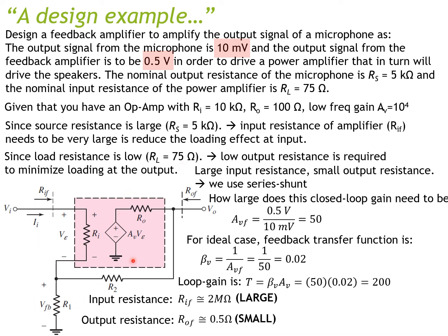So in this whole circuit here, what can you do to design? I mean, what parameter do you have to change to meet all of these values? So in here you only have control over, because this one is given, right? You cannot change in here. So you only have control over R1 and R2. So if you can find R1 and R2, or at least a ratio between R1 and R2, you can finish the design. And that would be beta, right, from this design specification.